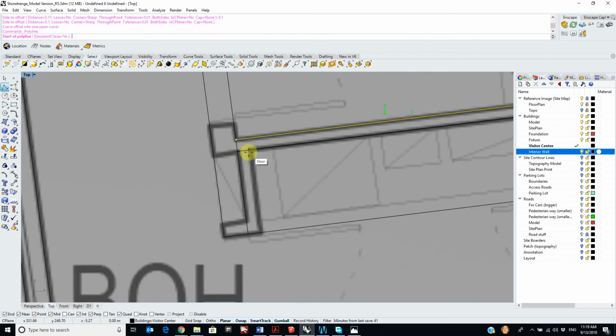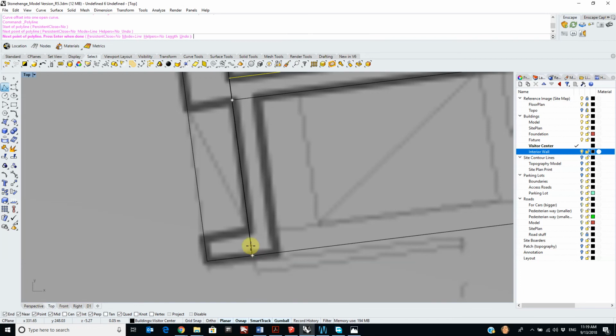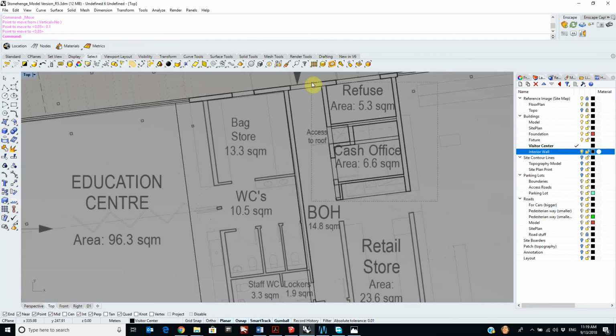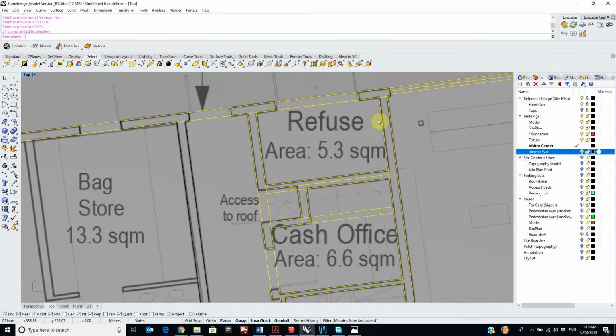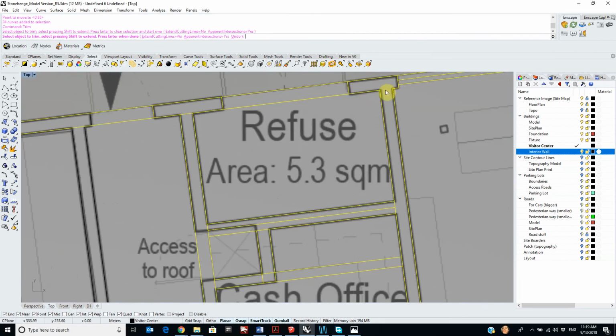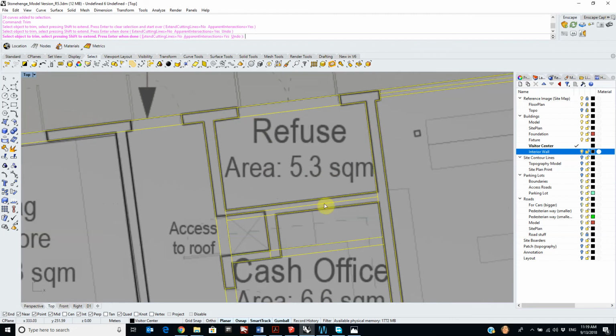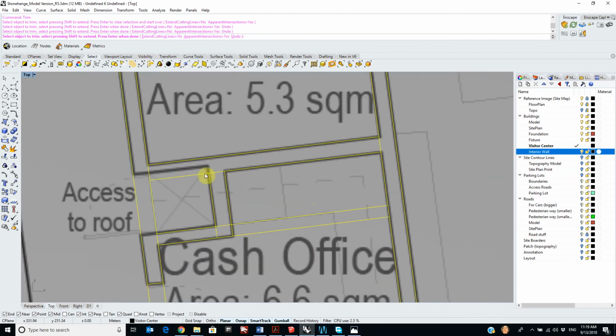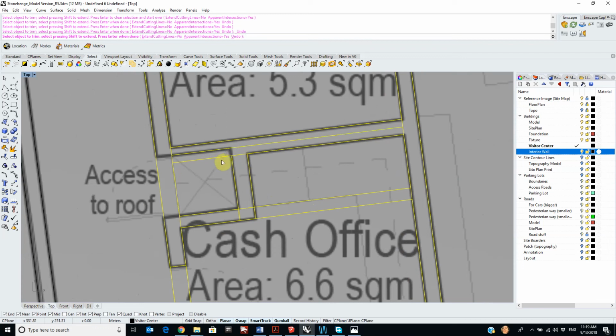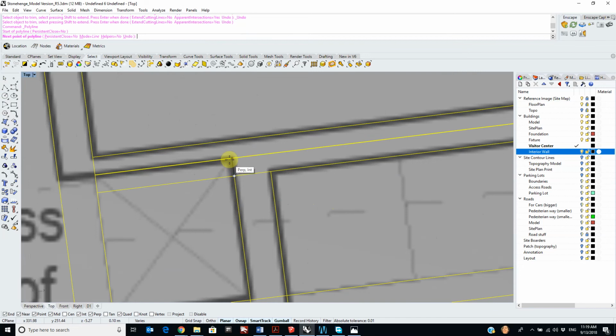and to just make sure that this line is clean as well, I'm gonna draw it like this, move it 0.1 in this direction, drop it. Okay, now we have to trim it. I'm gonna type trim. We don't need those lines, right? Okay, this line. We need to draw a line here. Okay, now I'm gonna select it and trim again. So we didn't need these lines.